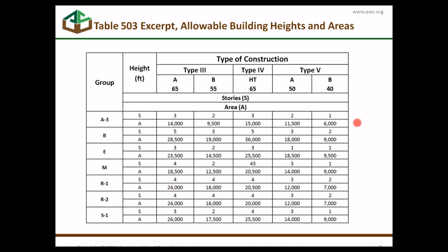And when we look at the International Building Code and we look at this table, we all start here, of course, and we see right away, oh, let's say group M, mercantile. Well, for type 5B, which is unprotected wood frame, I can have 9,000 square feet in one story in regard to a mercantile building. Now, wouldn't it be great